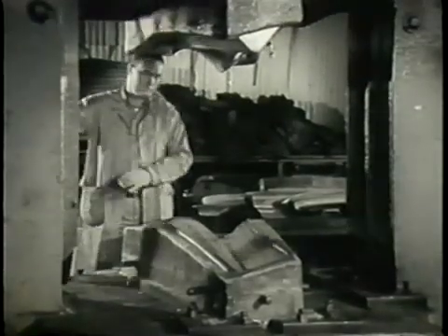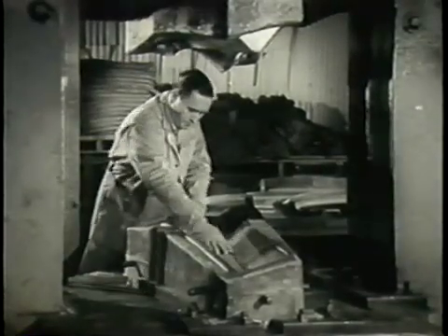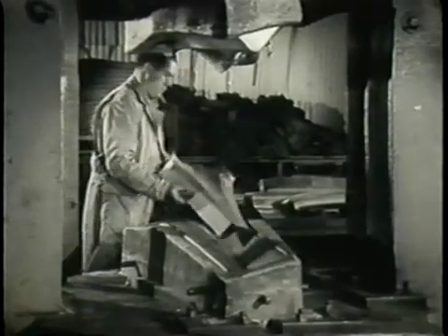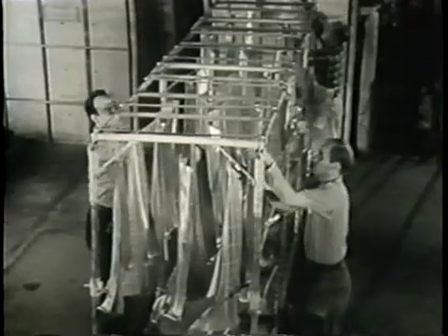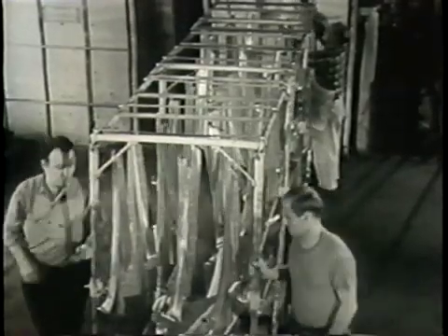The fact that severe cold working results from such operations as drop hammering and deep drawing gives rise to the need for an annealing or softening process between blows or other forming operations in order to prevent rupture of the parts.